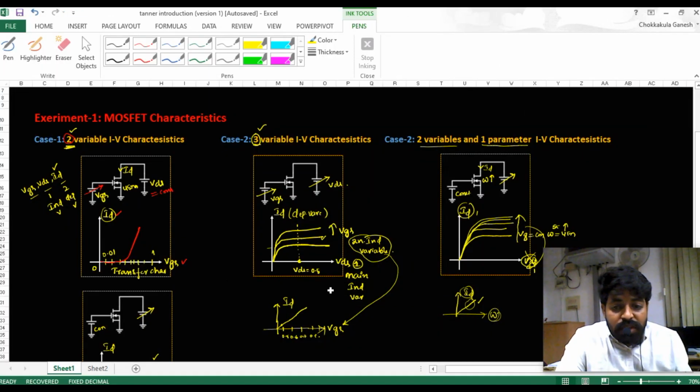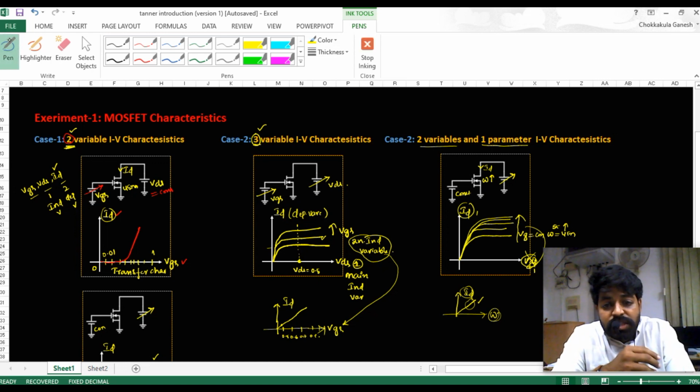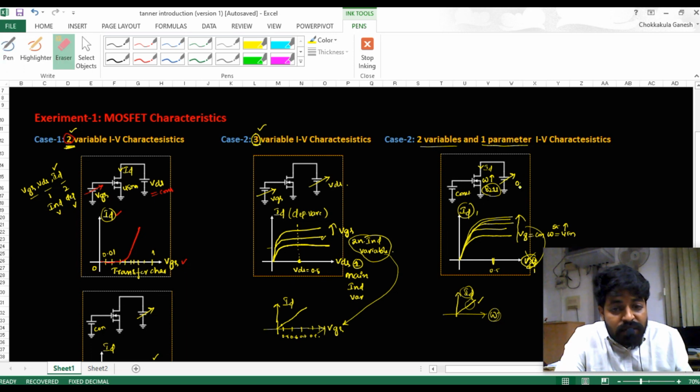So now my question is, when the transistor is given like this, where I need the drain voltage to be 0.5 volts, I fix it at 0.5 volts, and what width do we have to keep so that the drain current will be 82 micro? So 82 micro I want to flow across the transistor. I keep 0.5, or else I keep 0.4 volts, let us suppose, right? So now when I keep 0.4 and I need 42 micro, what is the width we have to keep? That is my question.